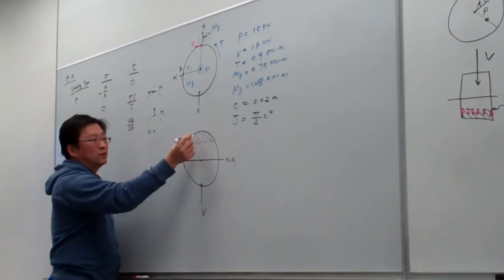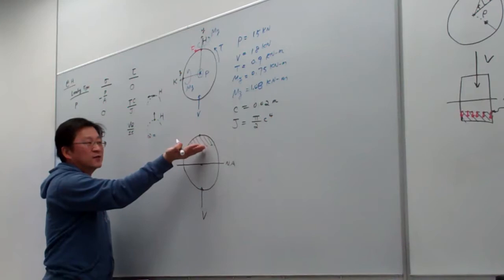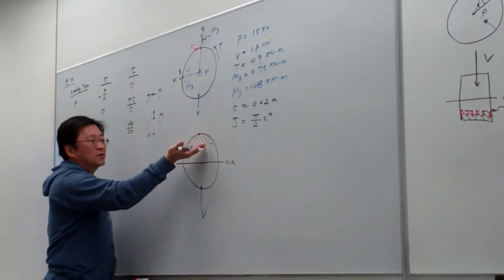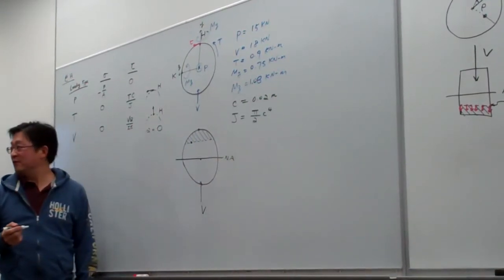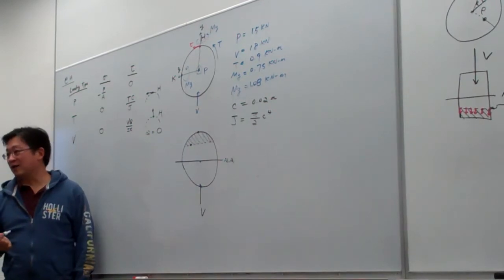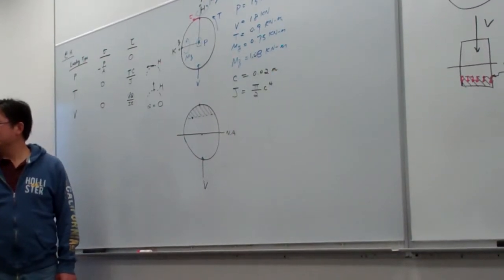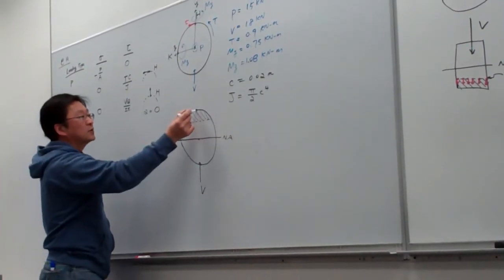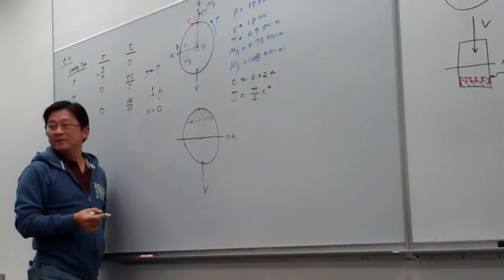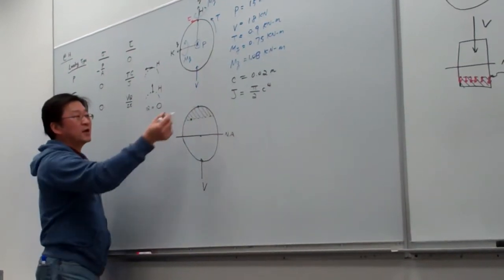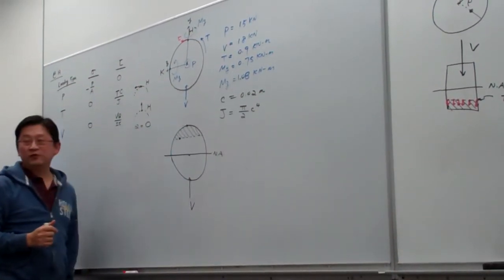And now you look at this one. Now the point is at the top here. So basically, as this point converges to here, this cut approaches the top. So basically Q will be equal to 0 at point H. Can you see it? So then tau will equal 0. Because the point H is here, if we selected the cut, it would be something like here, right? So this cut will take the whole entire cross section or nothing. But either way, Q will be equal to 0.